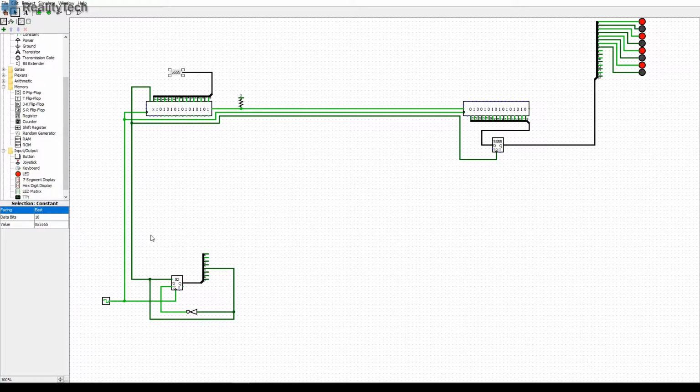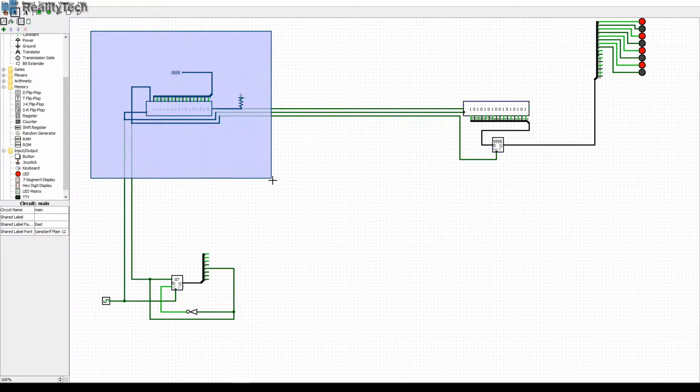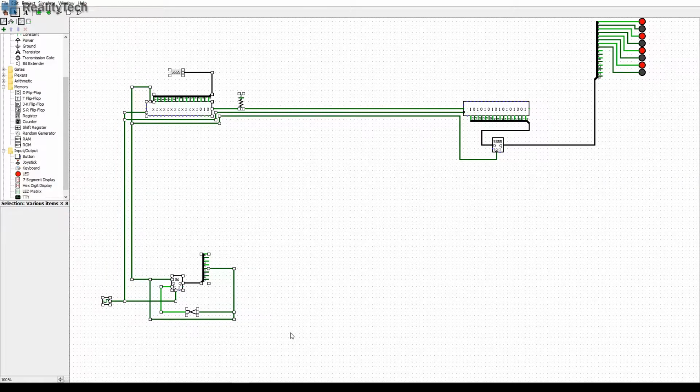This is more complicated than it would be. I mean, if you look, we've got 1, 2, 3, 4, 5 chips there. We've got the pull-up, we've got the register, we've got the splitters. These are not all things that would be in the real setup, unless you wanted to do it this way. But you would generally use your counter and your shift registers. Your latch enable is generally built into the shift register. So this entire section here can be completely built into a micro, done in software. So that then gives you your 16 outputs in this case with one chip.